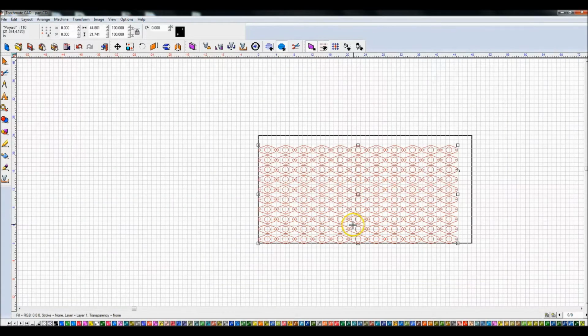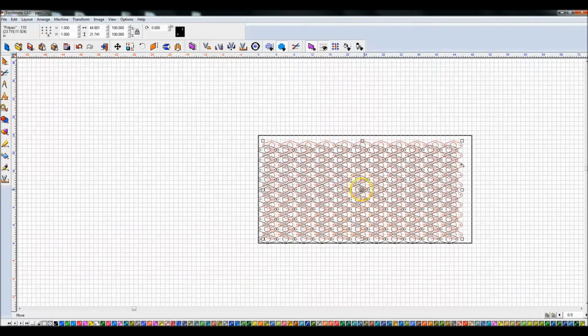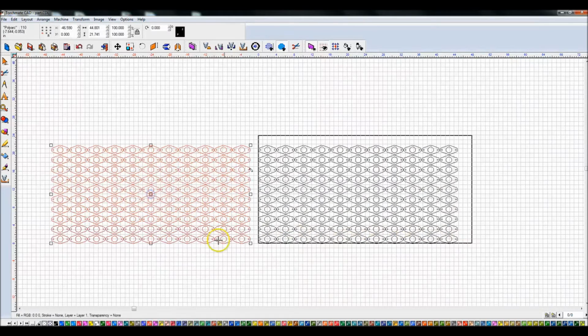Let me just go ahead and duplicate this with a Control D, pull this off here. Now nesting is going to take your existing parts and try to nest them on the sheet. By default, your sheet, if it is never specified, is your layout of your table here. I'm a 2x4, so what I'm going to do is I'm going to highlight all of these parts though.